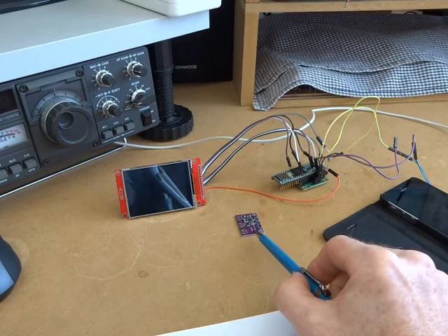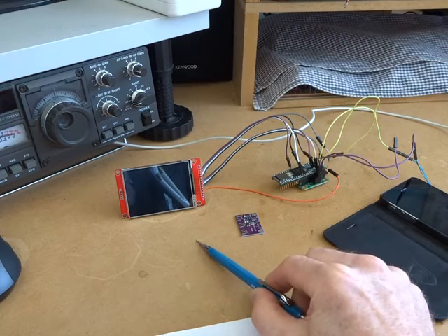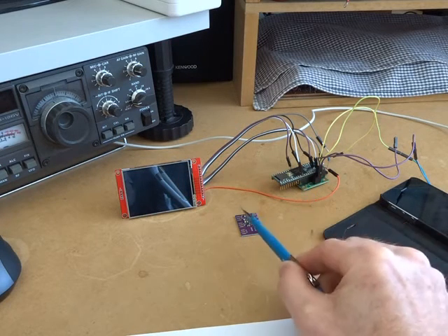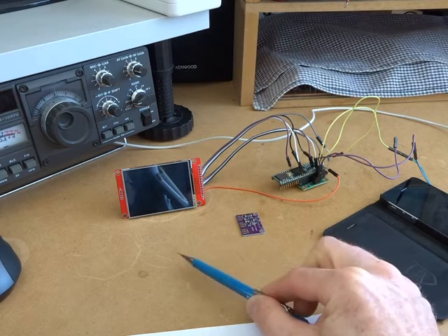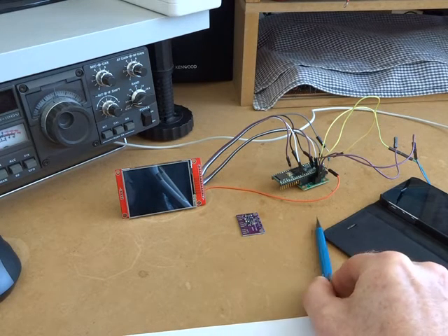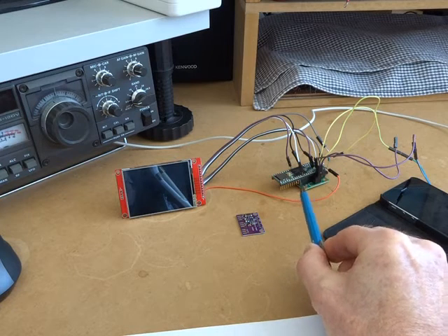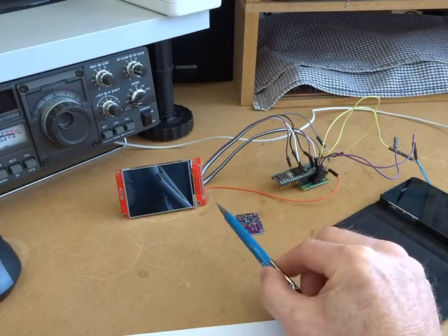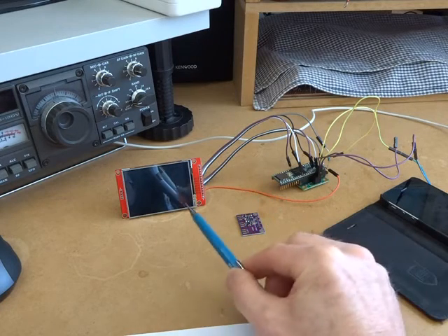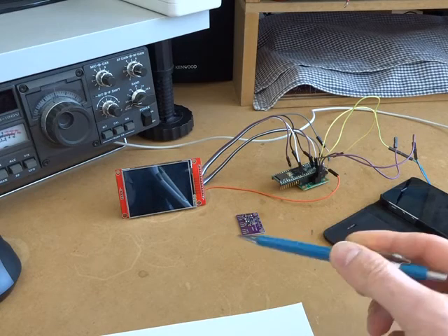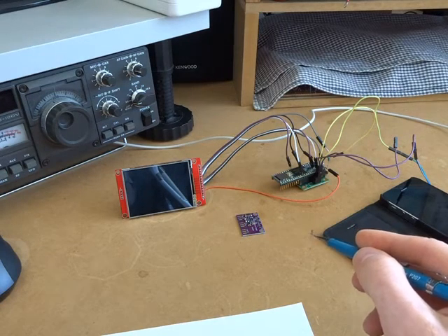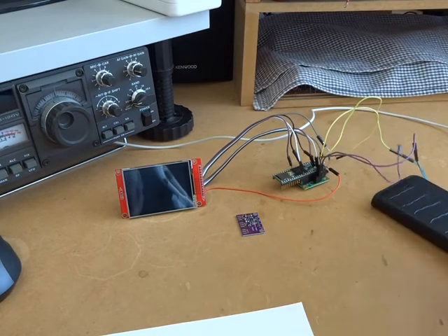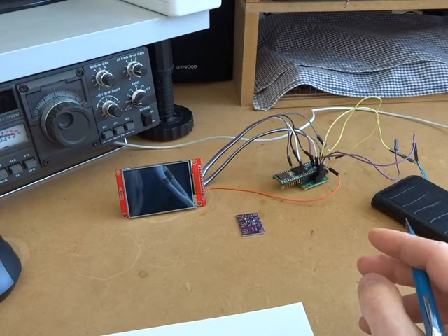I'll have the Teensy control that into another mixer, bring the RF from the IF down to AF, and feed into there. Do that, as we just explained, over 5 separate LO frequencies to produce our 5 FFT analyses, combine those all into one big array, and then plot every second element on the display. So that's the next step. We'll see how that goes. Got a couple of business trips coming up over the next week or two, so it's going to be in and out again.